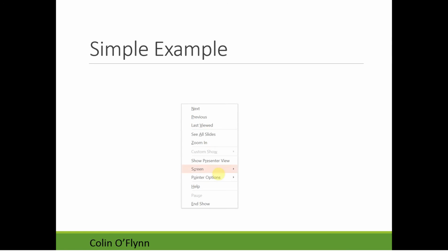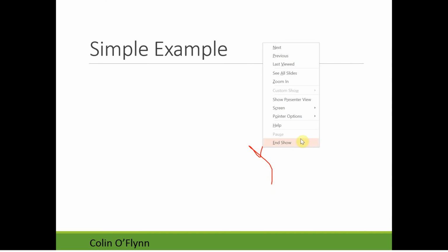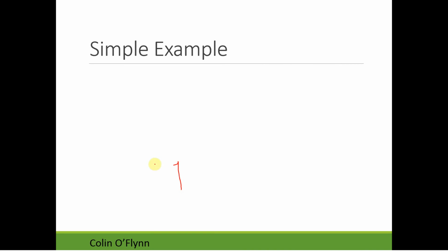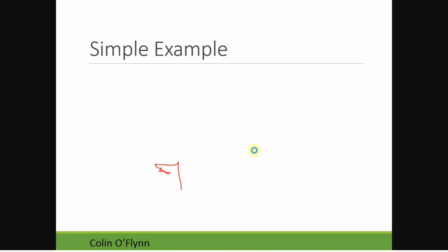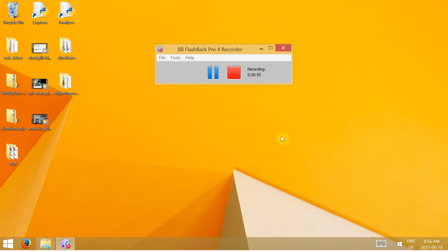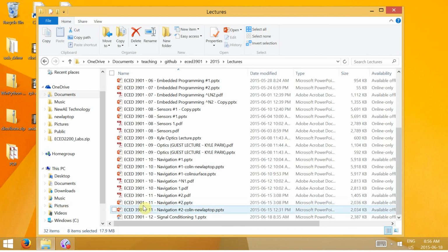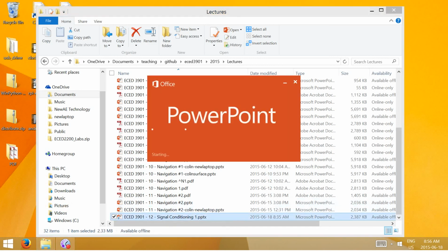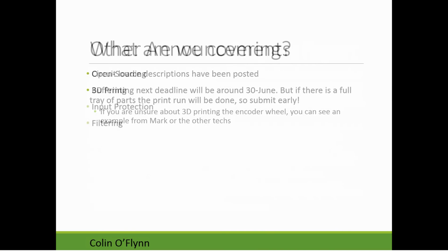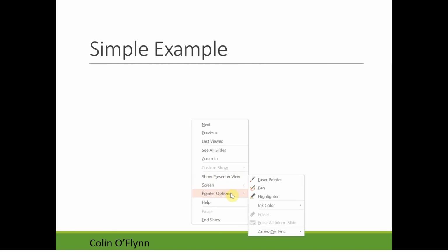So the first thing I'm talking about is circuit loading. What this is really is the question of if you have a simple voltage source or something like that, and you go to measure the voltage across it, you could get the wrong answer if you fall victim to what's known as circuit loading.